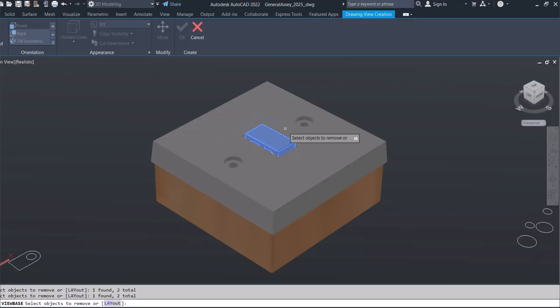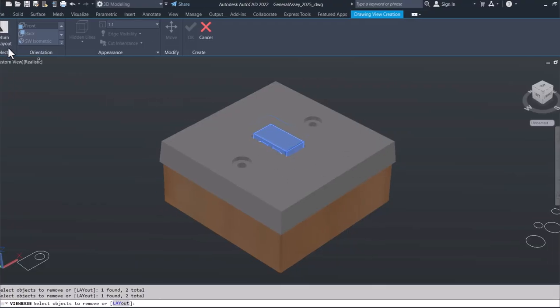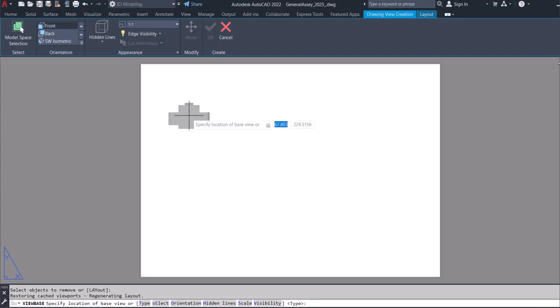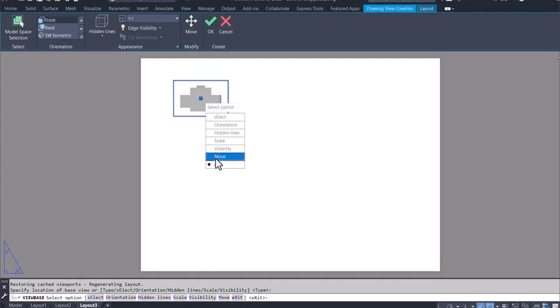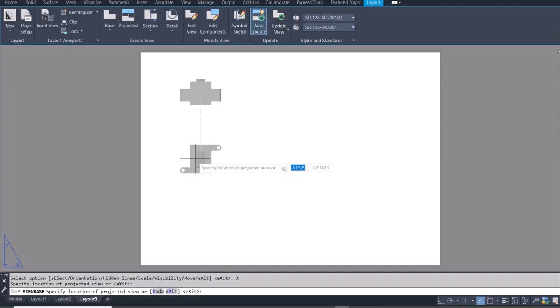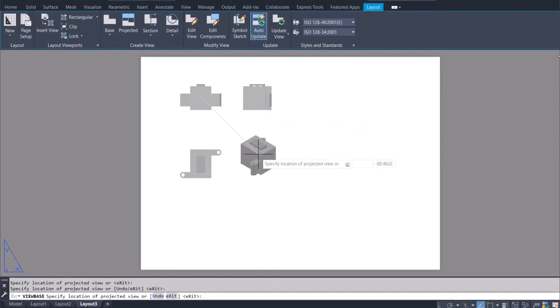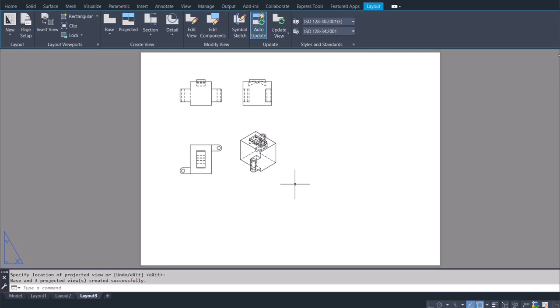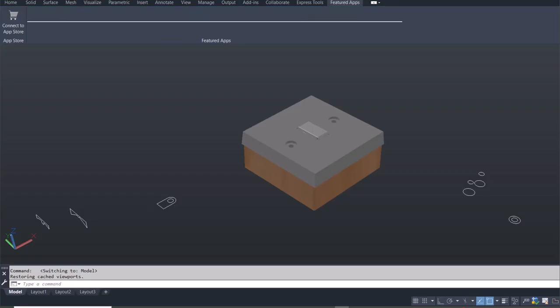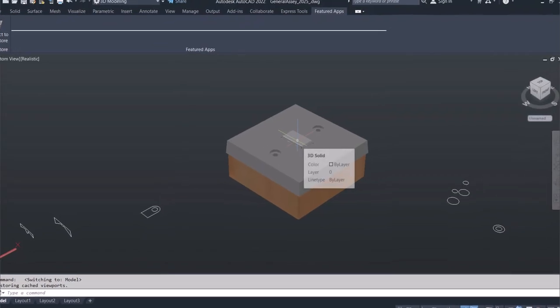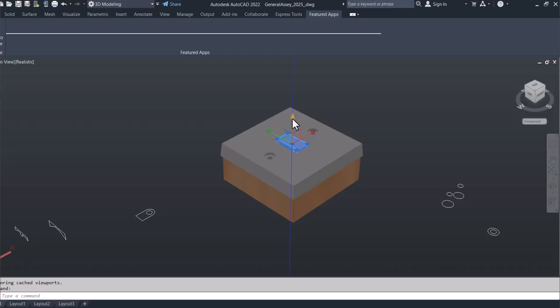So the best way to do this will be for you to explode it so that you can get the component you want. So this is the switch. I have the switch, I can just return, and then in here I can just drop them. Again, like I said, what you are getting is the toggle and the switch together, if you can see. So what you may want to do is, if you went to the model space, you can now maybe get the switch alone and then move it up a little bit. Let me move it up by 40, like that.